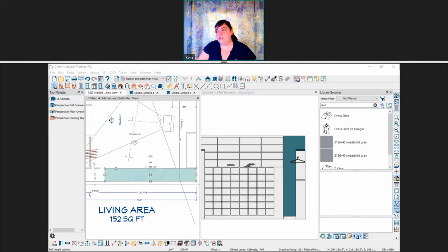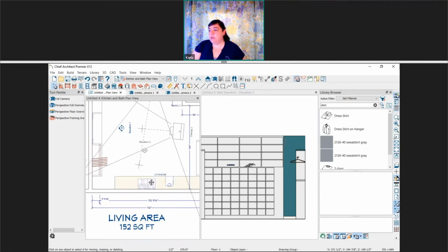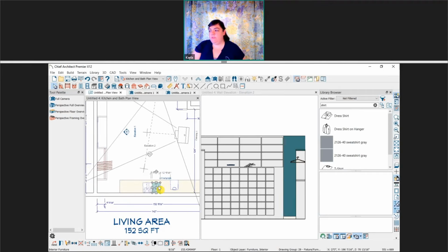And then just one other little tip, using transform replicate is another really handy tool. And the reason why I really like it is that if I'm in my plan view right here and I want to move something along the Z-axis, it's really the only way in a plan view to be able to move things along an axis that I can't visualize, other than opening the object itself. But sorry, Al, did you have something to say?